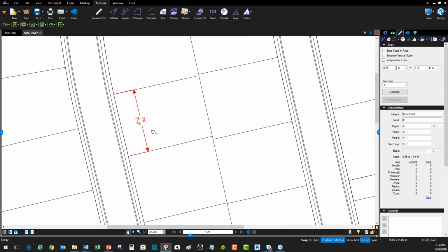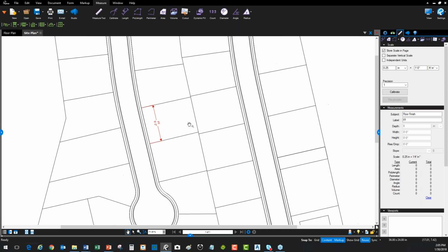But that's okay, because it's important to understand that Bluebeam is going to take this into account. A very common problem we run into when dealing with PDFs is that people don't scale them. They take a 30 by 42 document and figure, you're only looking at it online anyway, it doesn't need to be to scale, right? So you get from the architect or the engineer, whoever the sending party is, something they printed on an 8.5 by 11 sheet, figuring you're only going to zoom and pan on the screen. Well, how do you take that and go the next step into actually scaling this? We're going to talk about that in just a minute.